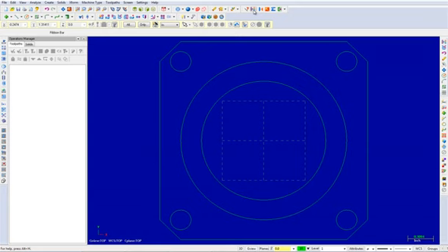You should notice that the lines in the two big circles are broken into 2 and 4 segments due to the mirror command. To be able to select the circle for the Circle Mill toolpath, you will have to join the arcs. Now we will join the entities. The join function allows you to join collinear lines, arcs that have the same center and radius, or splines that were originally created as the same entity. Select Edit, Join Entities.